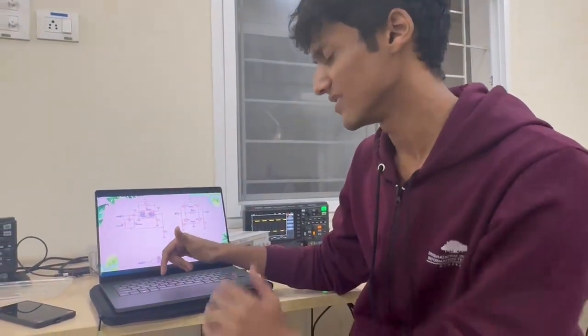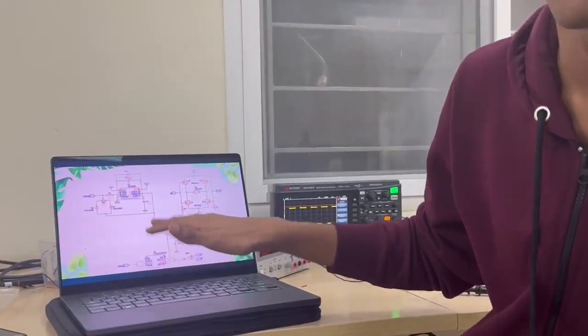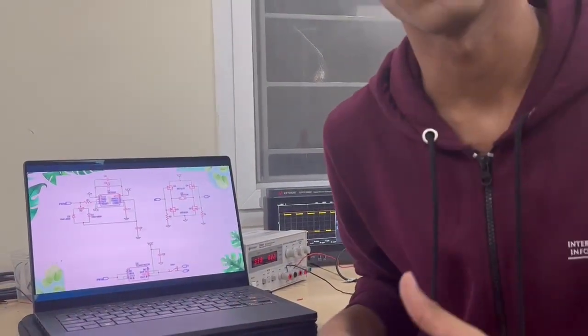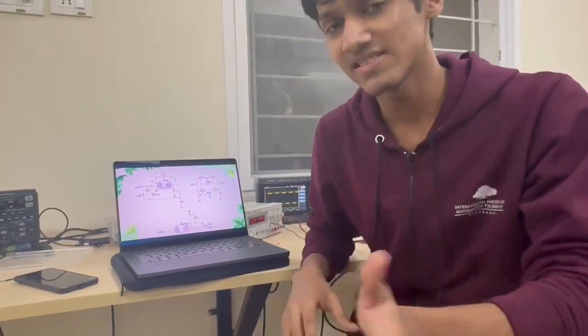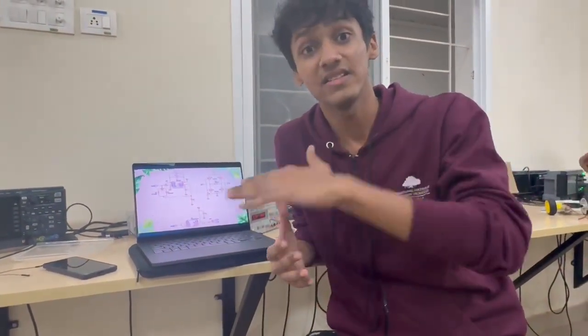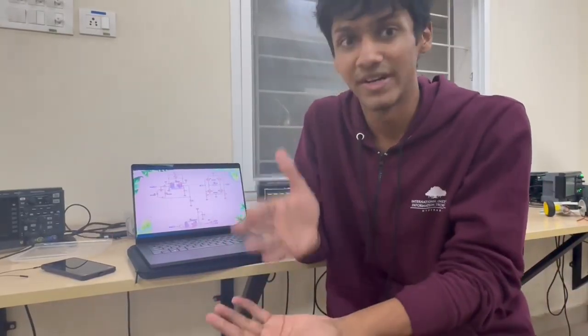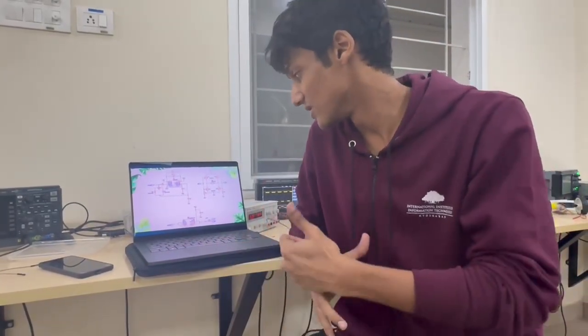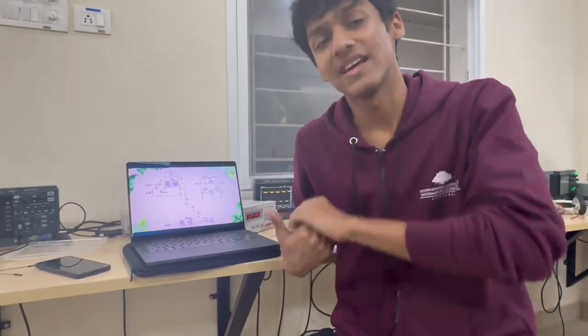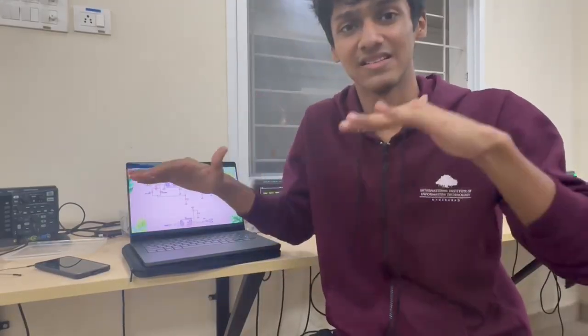For the second part of our circuit, we have a MOSFET driver. Our initial plan was to use a TC4427, but we only got a TC4426. The only difference is that it's inverting, and the TC4427 was non-inverting. A MOSFET needs a lot of power to drive it, but the PWM signal we're sending is low powered. So the driver acts as a middleman to balance that power gap, giving power to the signal by increasing voltage or current. It basically reduces the laziness of the signal, and it's a game changer in balancing the power levels.